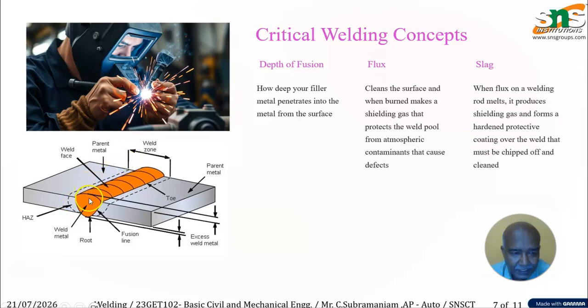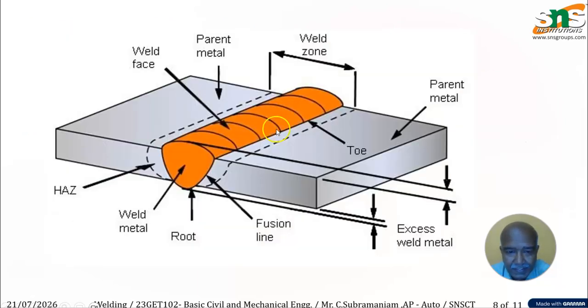On top, the heat is passed not through the whole metal, only near the weld metal itself. This excess metal projects on the metal sheet, and by a machining process you can remove it if needed. And there is fusion on the welded metal itself. This is a detailed picture of the welded metal.